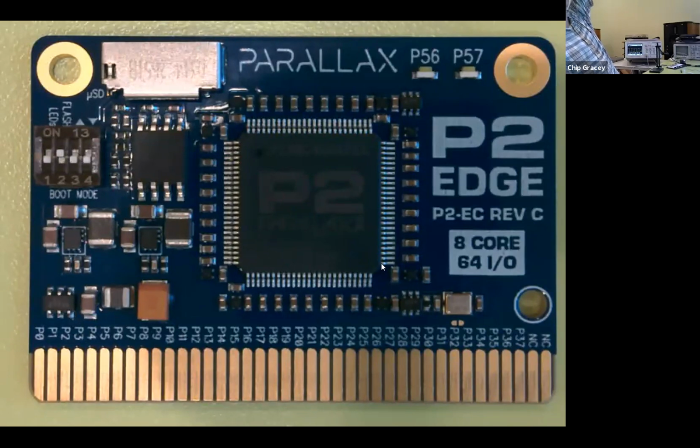So what comes into the XI pin now is a super sharp edge. It's about 1.5 nanoseconds rise and fall time. Before we had this 50 nanosecond period coming in as a sine wave from the crystal, and that was prone to re-triggering when there was high noise on P28.